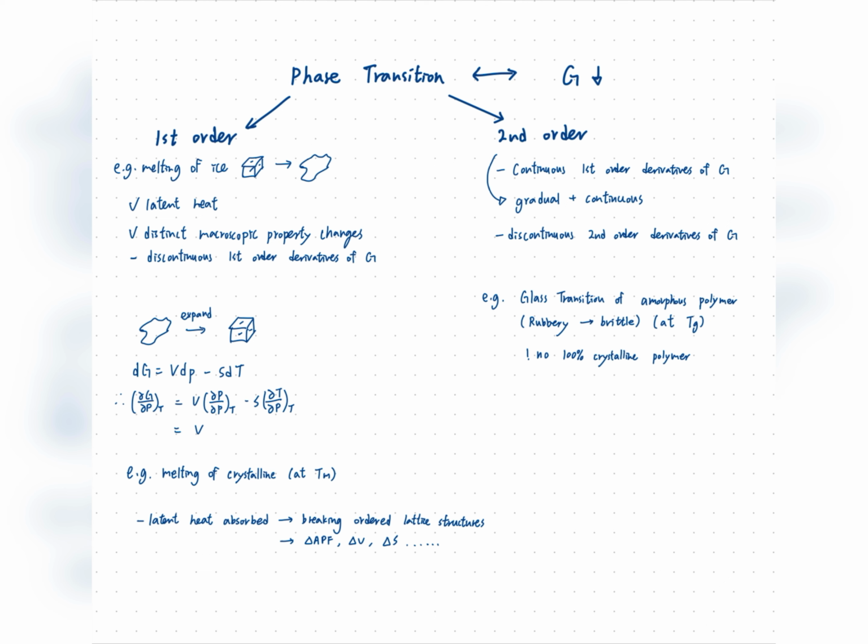By the way, it's difficult for all polymer chains to become aligned, so there is rarely 100% crystalline polymer. Practically, there are only amorphous and semi-crystalline polymers, which consist of both crystalline and amorphous domains, with intermediate properties between that expected from a completely crystalline and completely amorphous polymer.